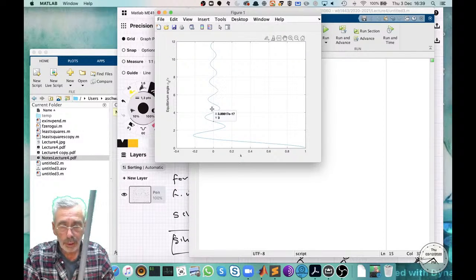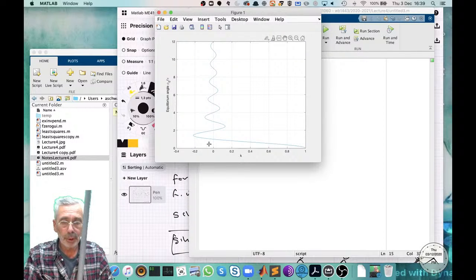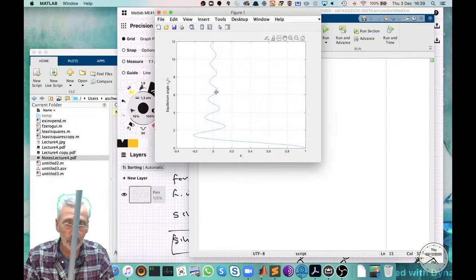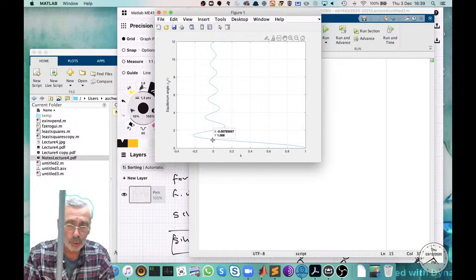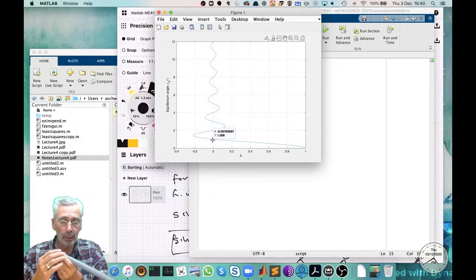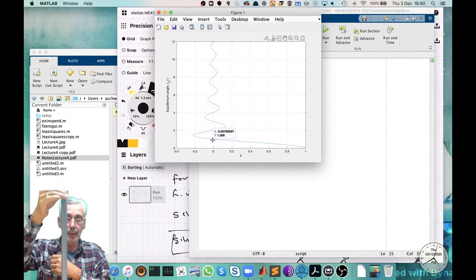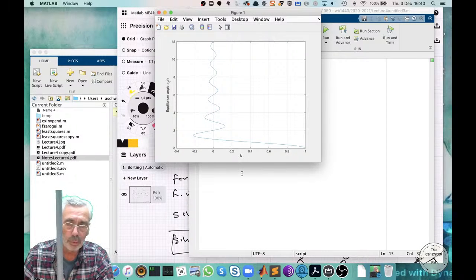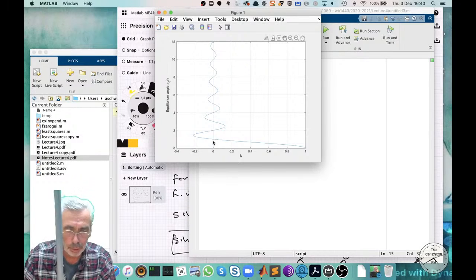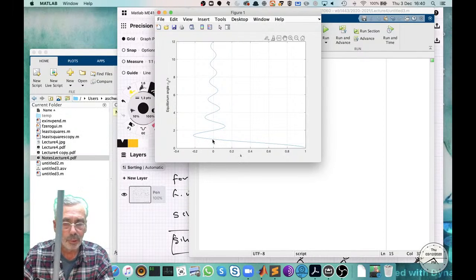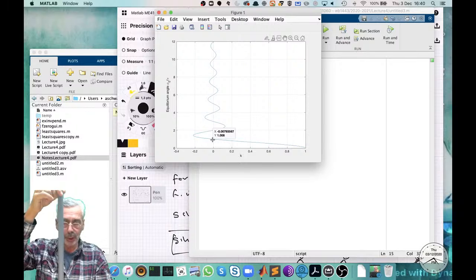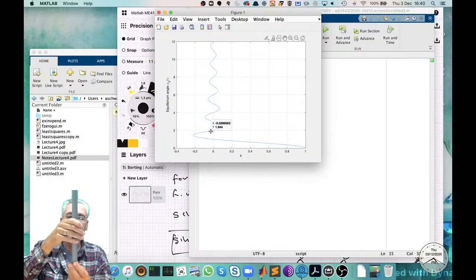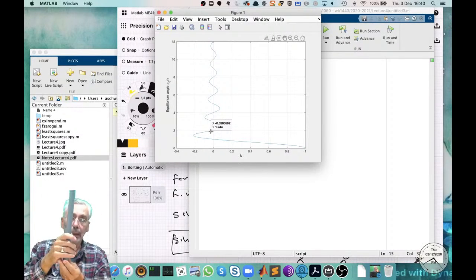Now, you can imagine that from some of these equilibrium positions, you know beforehand that they are unstable. So let's talk about the k is 0 one, there's no spring. I know, for instance, that the first solution with pi, this one, is, well, the first one is actually this, but that's a limit case, right? Because sine phi over phi, well, anyway, and I'm not going to talk about that later on, maybe, if time permits. Anyway, the first equilibrium solution like this, that's very stable. But then the second one, 2 pi, that's like this, that's an unstable configuration, right?